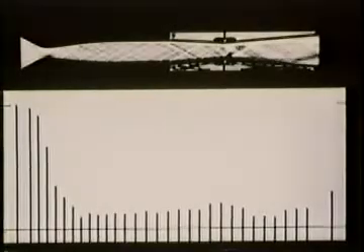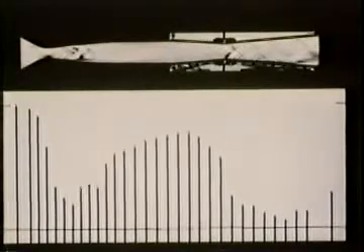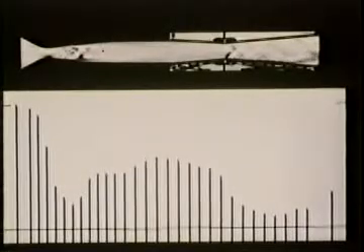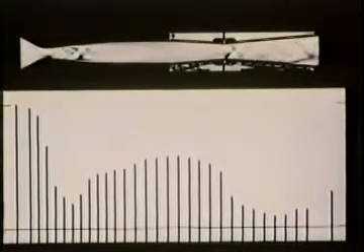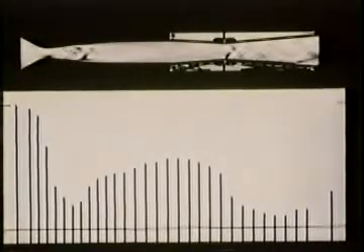It's possible to calculate from the wave angle that the Mach number in the test section is about 2.1, while the lowest Mach number we can get at the second throat is about 1.4. This time, watch the manometer as the second throat is closed to block the channel. Note the similar pressure distributions at the two throats. We again open the second throat to restart, and then close this throat as far as we comfortably can without blocking.